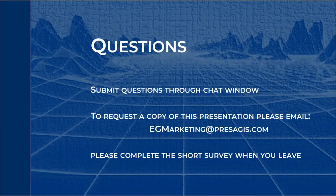Hey, that's a really good question. So again, this depends on what you're trying to do. If you're trying to do the point cloud processing that we talked about in this presentation, you start getting into the range where you want greater than 1 teraflop of processing. So for example, if we have a 60 hertz update rate, that gives you about 16 gigaflops per frame to process data. So that puts you in the gigabytes per second range of data that you can process per frame.